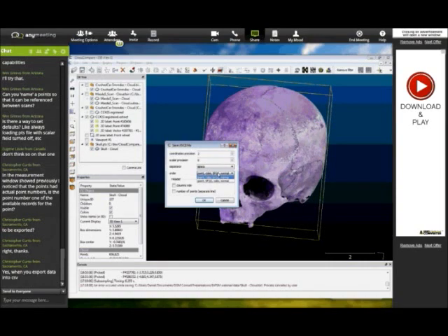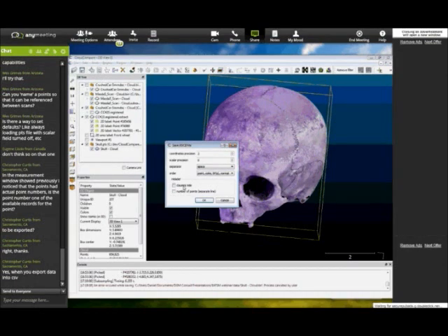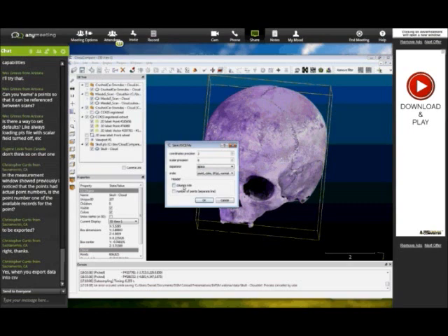And eventually, you can check those two checkboxes. The first will write a small header with the name of each column. And especially, it's a good way to save the scalar field names. The other one will make CloudCompare save in the very first line of the file the number of points that are going to be saved. It's also very important for some software and in the PTS format, I think.